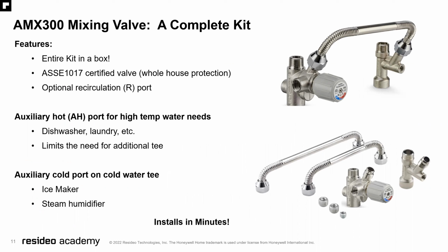Eliminates the need to have an additional T. And it has an auxiliary cold port on the cold water T for ice maker or steam humidification. It took me longer to go to the store and get the necessary plumbing connections than it did to actually install this guy. It does install very quickly and very easily.